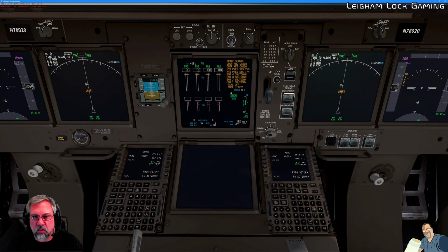And there's a very easy solution to that. You can do it using the cancel recall. Now, just to make it simple so we can see it here on the screen, I'm going to take control of the ECAS display by turning on the control panel here on the right CDU. So we turn that on, and now I can take control, the display control, activate that, and now I have the cancel recall option available to me.